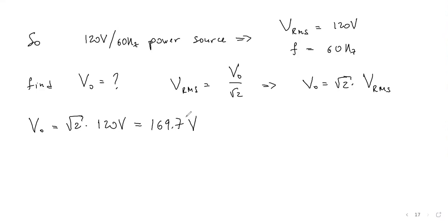So when you plug something into your power outlet, then you should understand that the voltage is oscillating between negative 170 volt and positive 170 volts, yeah? It's not 120. It's 120 only on average. And technically, it's not even average, it's RMS. So it's a standard deviation from the zero.